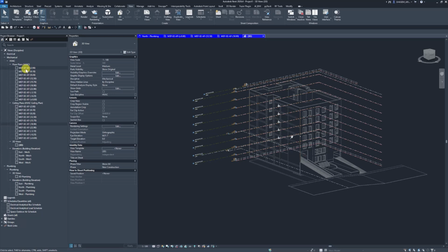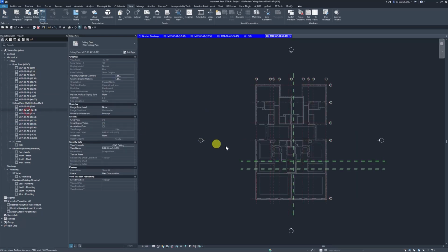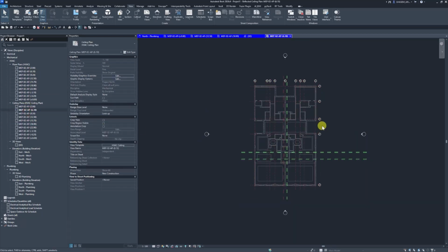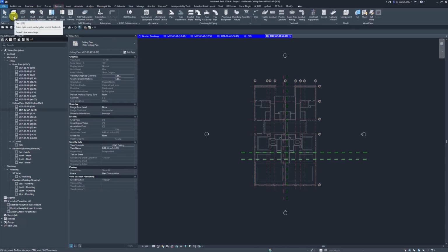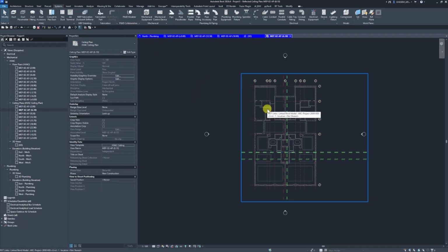MEP-related processes. And guys, by the way, what I actually recommend for really starting the project would be setting and placing the required equipment first. Talking about equipment like diffusers or basically any other mechanical equipment. Well, anything that you actually need for your project. And then after adding the equipment, from the System tab, you can select, for example, duct and start adding them to your model.